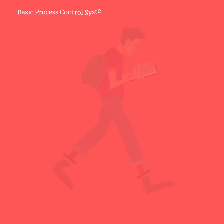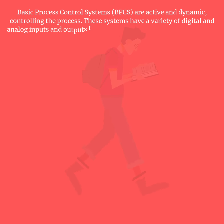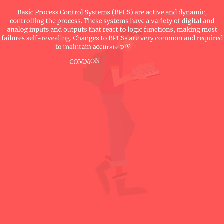Basic process control systems, BPCS, are active and dynamic, controlling the process. These systems have a variety of digital and analog inputs and outputs that react to logic functions, making most failures self-revealing. Changes to BPCSs are very common and required to maintain accurate process control.